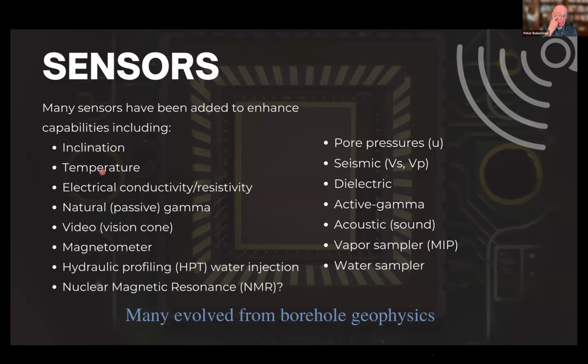And then temperature sensors were added. The awareness that although the strain gauges are very accurate inside the cone, they are slightly temperature sensitive. And so I lived in Canada for a long time, and although the air temperature might be quite warm, the ground temperature is usually quite cool. And so in Canada, of course, the water temperature can be very cool.